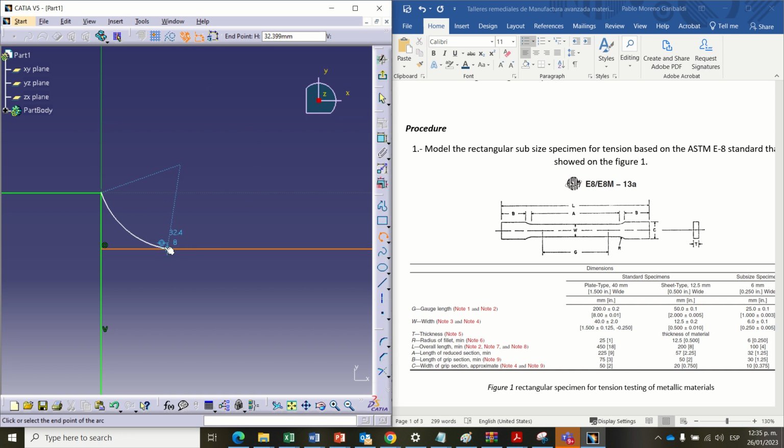But look here, as you can see, over my final point of the arc it is appearing the symbol that we have contact. Remember, it appears in blue, formed by two circles and crossed by a horizontal line. In that point, we have contact, but we don't need only contact, we need tangency.